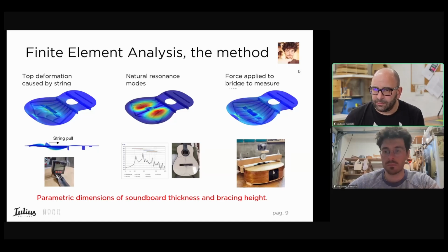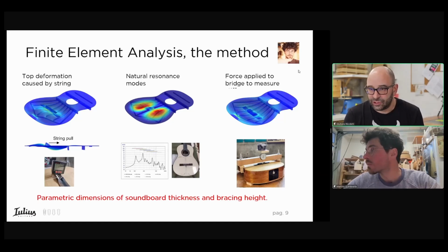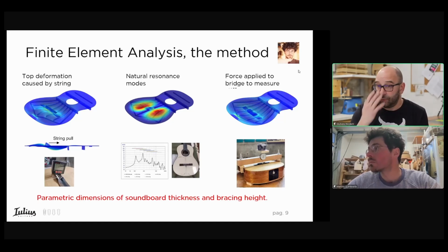So Jose Luis is asking a similar thing: can the top be clamped closed to get a ballpark mountable frequency to easily curve the braces? Yeah, it's the same thing. I mean, if you want to clamp the top on the body, again, pay attention to how you're doing this, because it's just mechanical. The way you are coupling the soundboard with the support, and the way you are constraining the edges of the soundboard, is really affecting its vibrational behavior. So you just have to design a method that is repeatable, and pay attention to the doming on the sides.